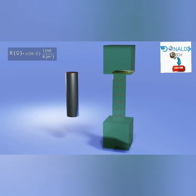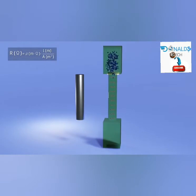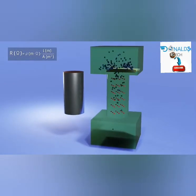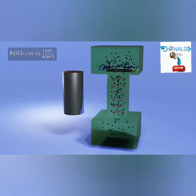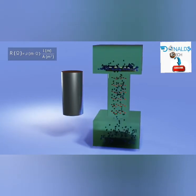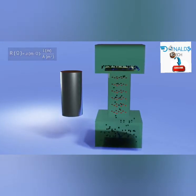The next two variables are easier to understand. If we have a greater distance to travel in the pipeline, it is logical that more time and effort is required to get to the other extreme. That is to say, the longer the cable, the greater the resistance. On the other hand, if we increase the diameter of the pipe, even when the resistivity coefficient continues to affect the entire volume, there are going to be more possible ways for the electrons to pass. In other words, the greater the cross-sectional area of the cable, the less resistance to the passage of the current.